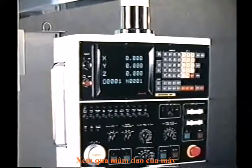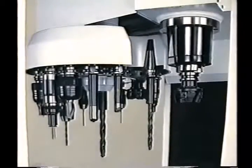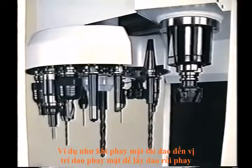Let's take a look at the tool changer on this type of machine. This is called the simplified tool changer. It does not have an arm to actually take the tool in and out of the spindle, and in programming, the pocket facing the spindle would always be empty, because when we asked for a new tool, the machine would always put the tool that's actually in the spindle into the facing pocket, rotate around to the tool we call for, and then exchange the tool.